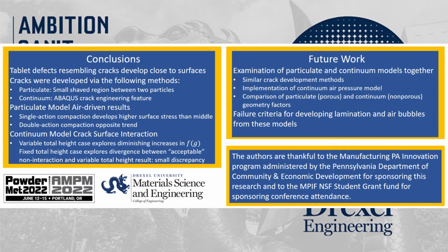In the two models, we examined a particulate model with discretized interstitial pressures and the development of a large crack in an axisymmetric high aspect ratio compact, representing entrapped air and lamination respectively. Though the particulate model is highly ordered with discretized pressures and has octagonal particles, these assumptions aid in computational efficiency for enhancing our understanding of the interplay between porous media and the pressure gradients driving air effects in powder.